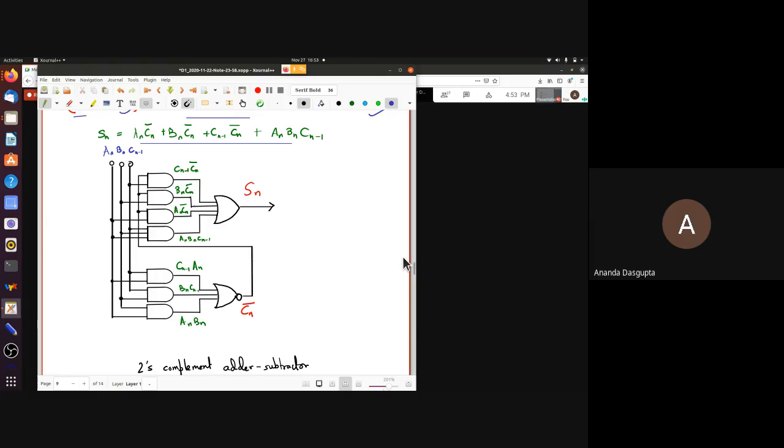The important reason why I wanted to talk about this is that you must realize that the Karnaugh map, or even getting the expressions in the simplest possible form, may not be the final step. Sometimes you have to be clever, and if you have multiple outputs, you may have to use those outputs together. So I gave you an example of a 7-segment display where we had 7 distinct outputs for the 7 segments, and we simplified each of the outputs individually.